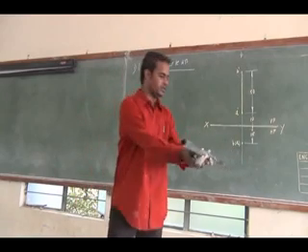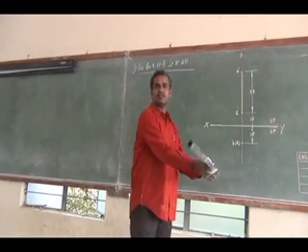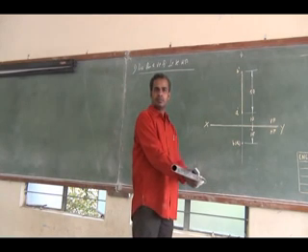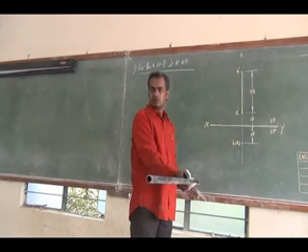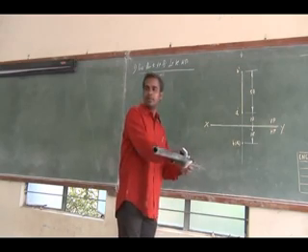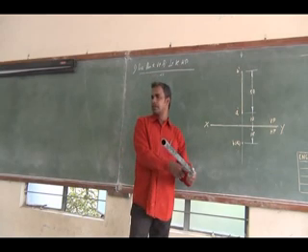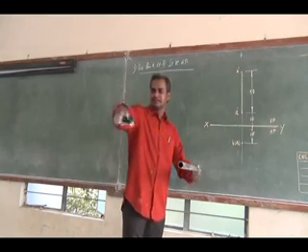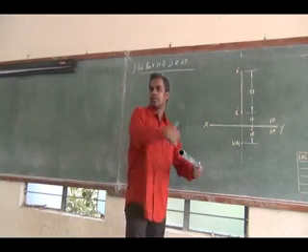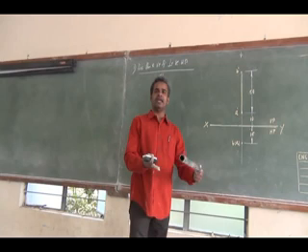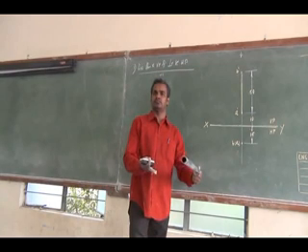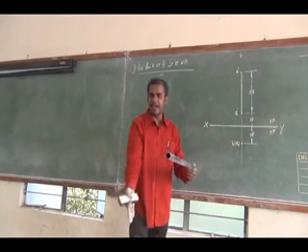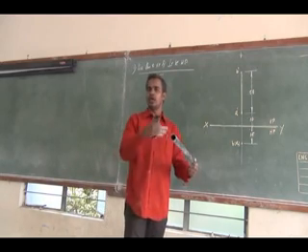Okay, see here, the nearest end is given. The end A is 10 mm, 20 mm above and 10 mm in front of, and the line is placed parallel to HP and perpendicular to VP. So where will I obtain my true length? Below HP, below the reference line. On HP I will obtain the true length.